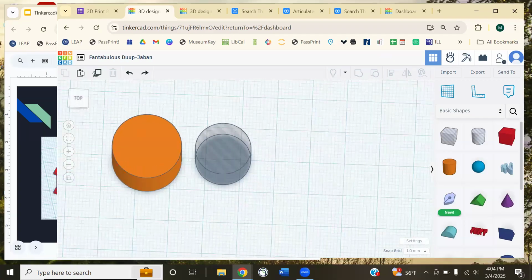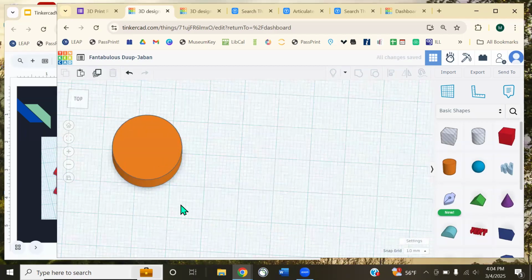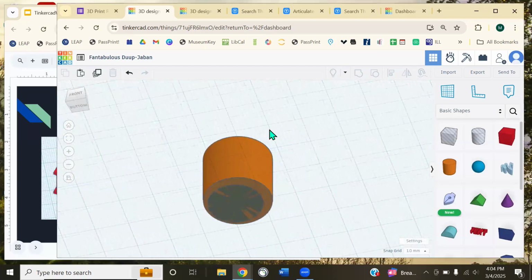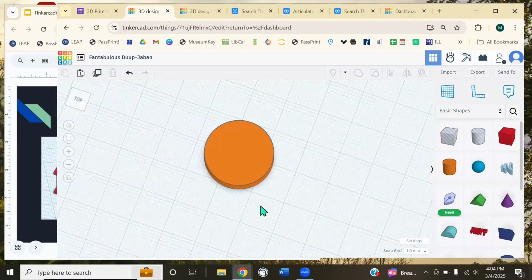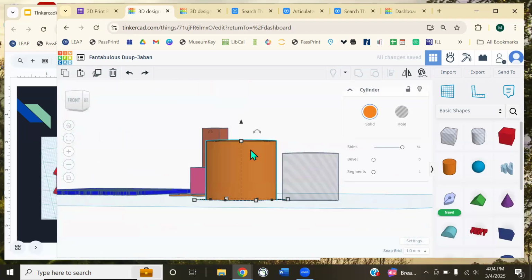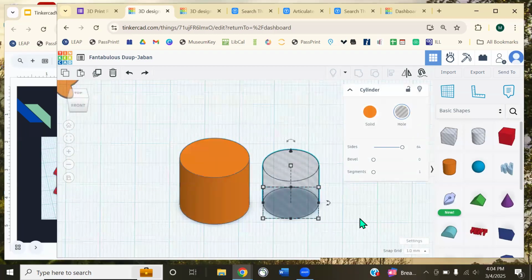So what I can do now is try and put it in the middle. We can see it kind of vanishes, but it's still inside that object. The issue is that when we scaled the whole thing down, it also scaled down the height dimension. I actually want to scale back up the height dimension itself, so we cut out both the top and bottom of this object.